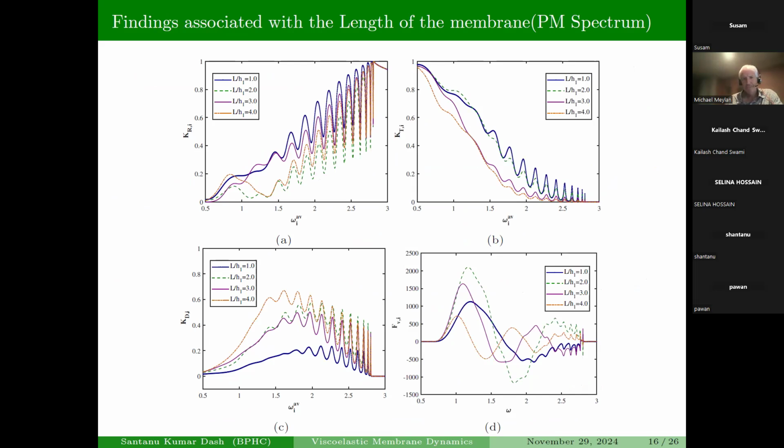As we can see, a sinusoidal increasing and decreasing pattern is shown in the Kr and Kt components. As the length of the membrane increases, the reflection effectively decreases for each of the regular components, and simultaneously the dissipation increases. So if you consider a long thin viscoelastic membrane with a suitable damping parameter, then it can effectively trap the wave energy from the random waves.